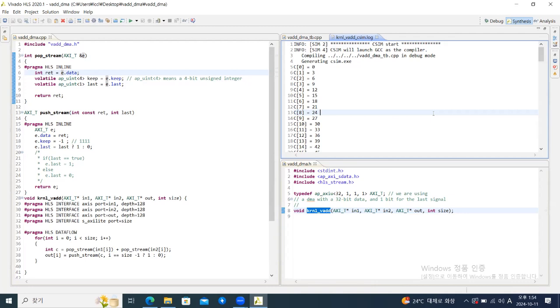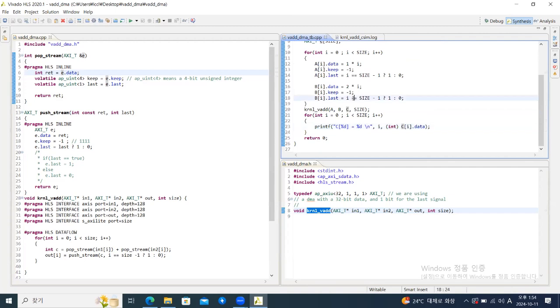So you see our test bench is getting a lot messier than expected, so we don't want to print the values every time. One trick, which I actually explained to some people at the second lab, is that return 0 means that the test bench finished with no errors. Everything other than the value 0 will be treated as an error.